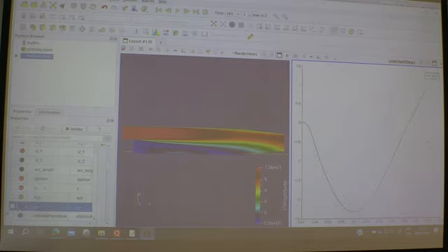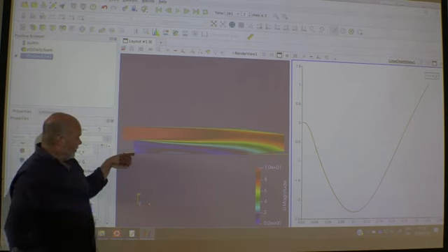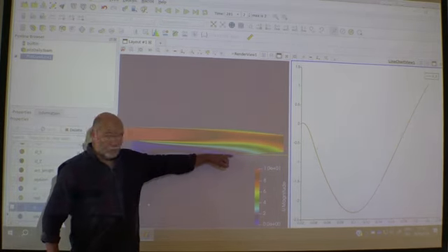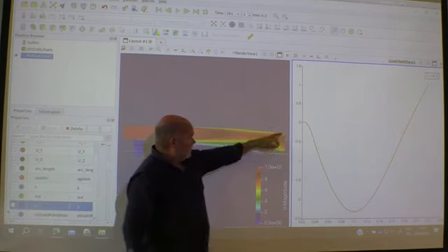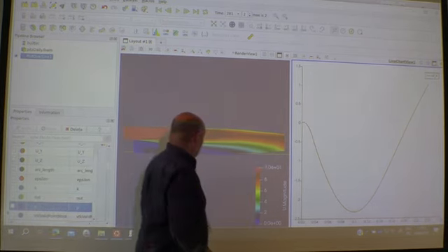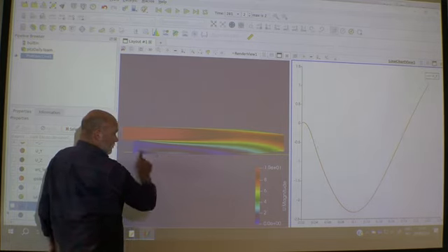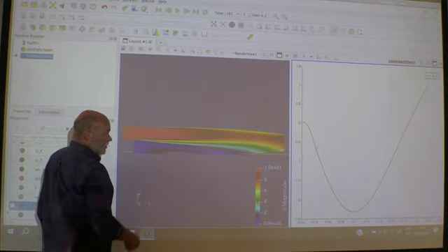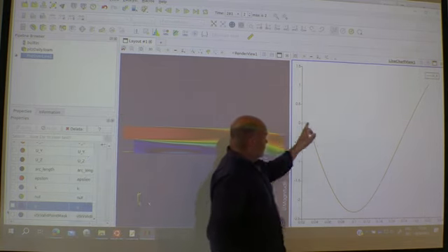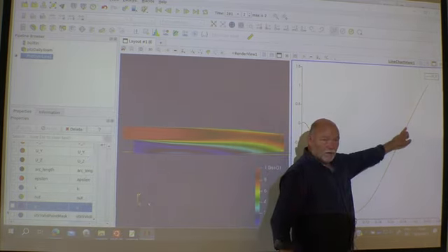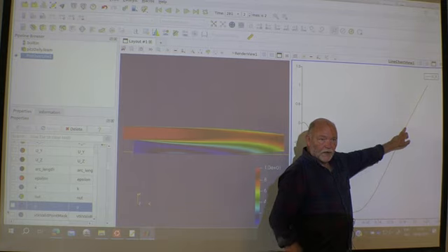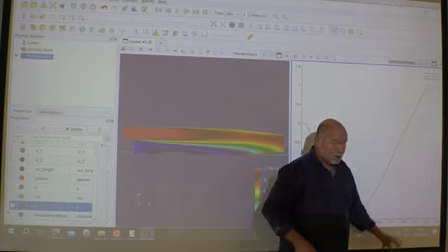There I have the velocity alongside this line very close to the bottom. So you see it goes negative. Makes sense, since you have a vortex here, you have a velocity in the negative direction. The question is, where is it zero and becomes positive? That's the reattachment length.